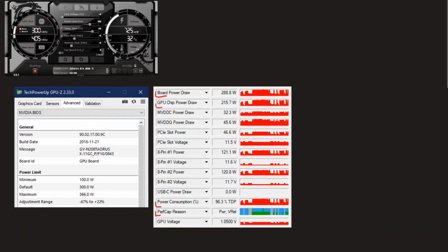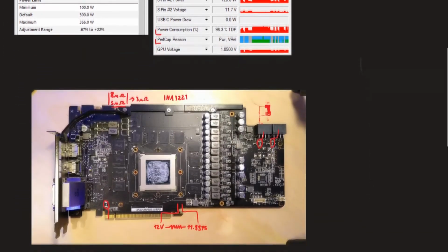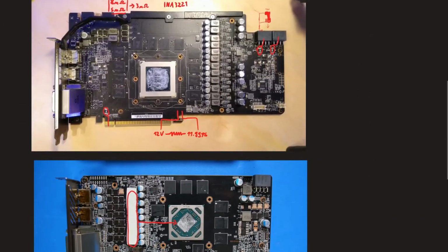So yeah, power limit is pretty annoying, especially on NVIDIA, but on AMD too. You can get around it, but if you're just a normal overclocker, this is overclocking basics, meant for beginners. This is more of a 'this is how it's done' and not a 'you should do it', because you shouldn't. Flashing BIOSes can be pretty dangerous, you can brick your card with it. Doing hard mods, well, I think the dangers of that should be apparent. Your warranty will be voided into nothingness.